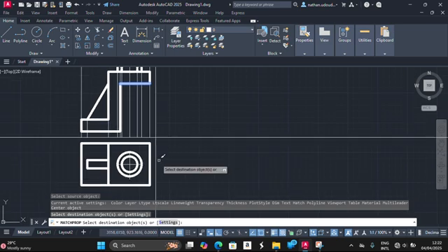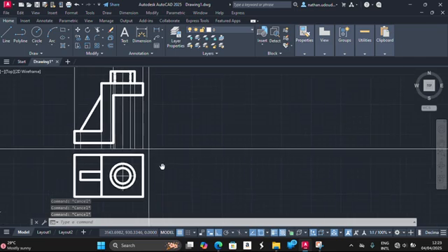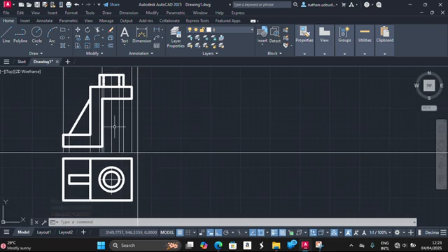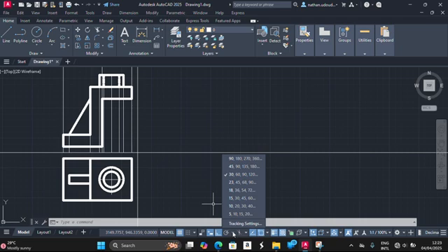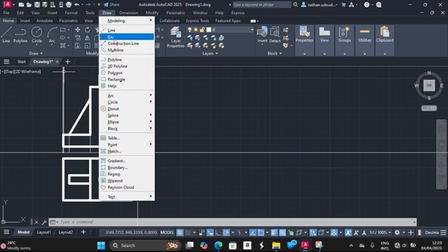So now we have done the front elevation, and we've also drawn the plan. So now we're left with the side elevation. So this is the front elevation, this is the plan. So now to draw the side elevation, we have to set your polar tracking, set it to 45 degrees. So after which you can pick up your ray command, come to your draw toolbar, your ray.